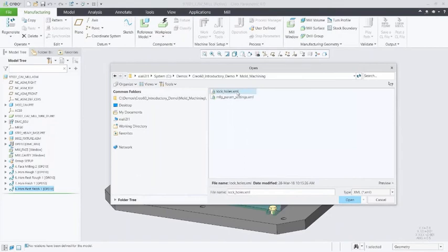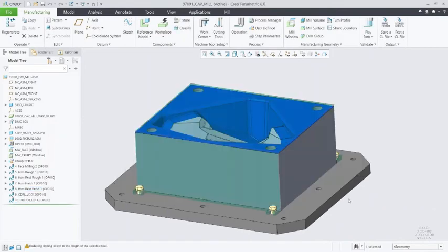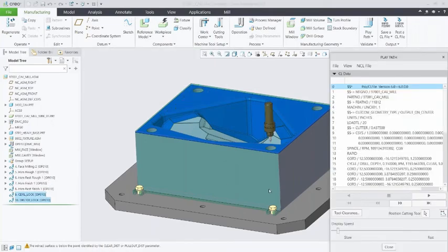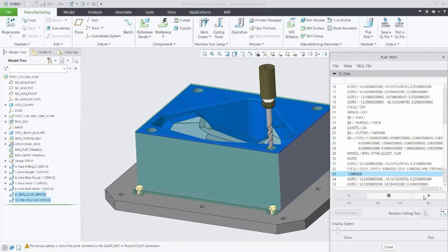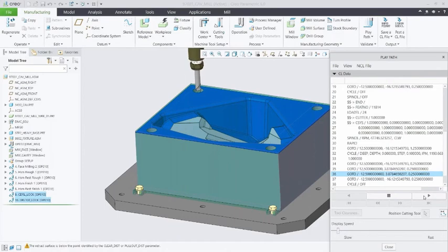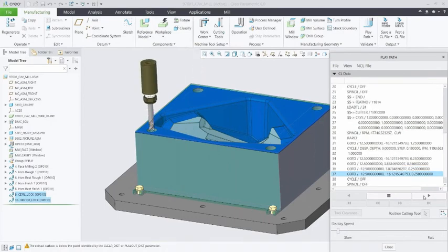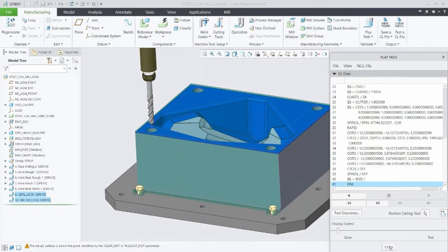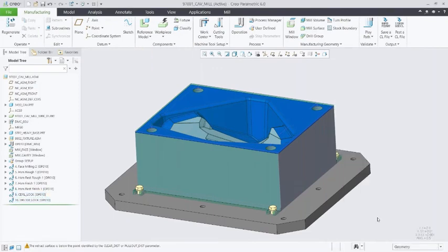If we want to bring up our hole template, we can either do that by the standard template, or the standard hole creation that comes with Creo. We can do that. If we'd made some changes to that standard hole creation and we saved it as a template, all we have to do is pull it up, and you'll see it knows the strategy, it knows the tool, it finds the geometry, those lock holes. We have those in all of our parts, for example, all those molds. So it knows what it's looking for, and it can do that for us.